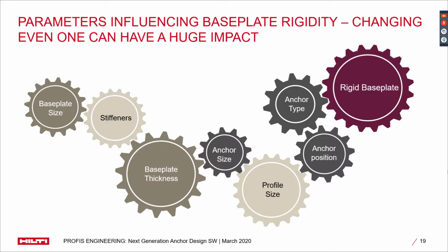So overall, as I mentioned, there are multiple factors that could influence the rigidity of the connection. So there is no black or white answer to this problem. All the factors were seen in this slide, such as base plate size, stiffeners, base plate thickness, anchors, and so on. So with that in mind, what will happen if the base plate deformation is not considered in